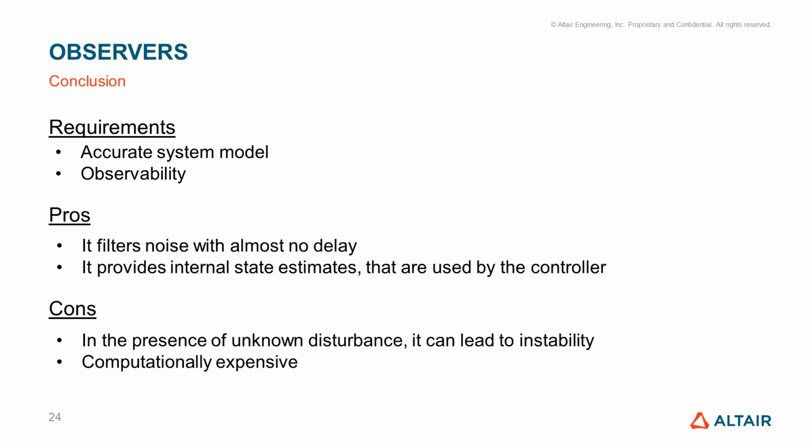Full-state observers can be deployed in case we are using cheap and noisy sensors, or if the system is placed in a really noisy environment. Instead, reduced-order observers can be deployed if we just need to retrieve those states that we cannot directly measure. For example, in our case, we have designed and deployed a reduced-order linear observer, which provides the velocity of the ball that we couldn't measure.